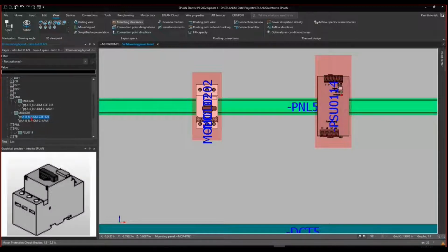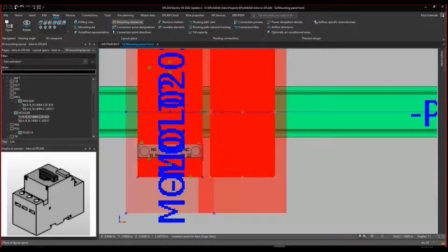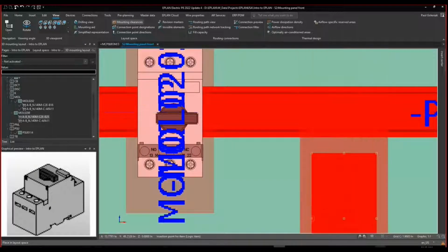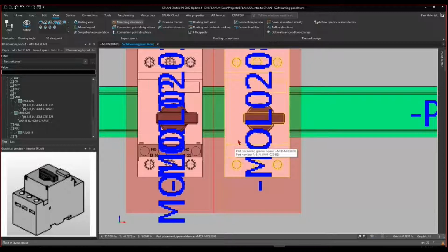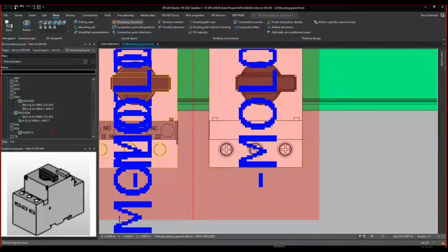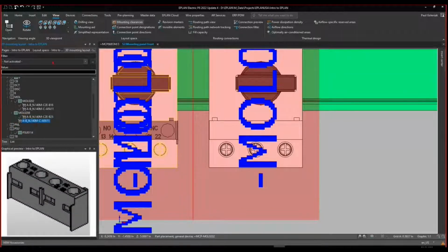Now let's place one at a time. So here I'll place the first part number. Make sure that I'm giving myself the appropriate space because of the collisions. So this is on a grid at the moment, so we can certainly change the grid to be a little bit better for us as well. But now it shows in the green check mark that this part has been placed, but this one is not. We can also set a filter for unplaced parts. So that way we'll know if there are any parts that have not been placed in the panel yet.